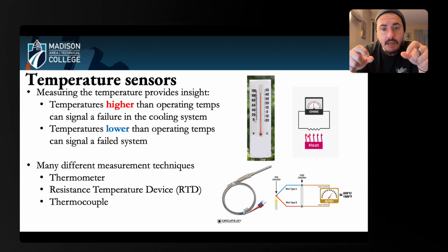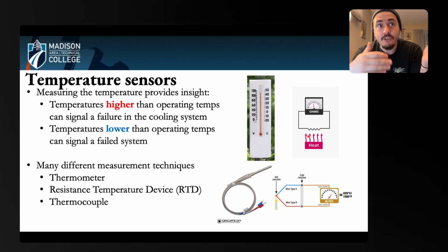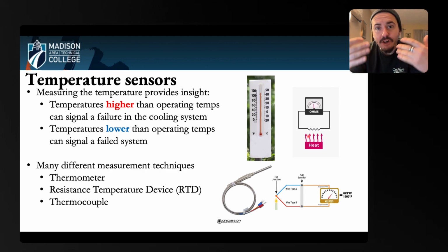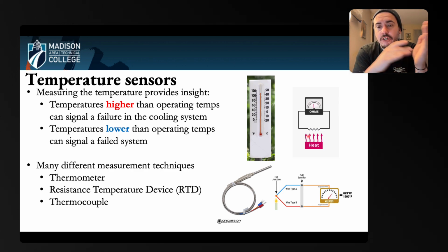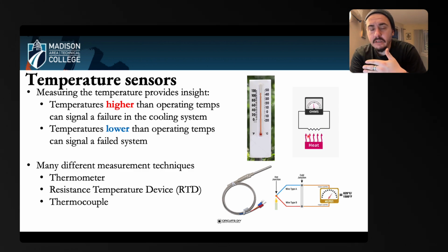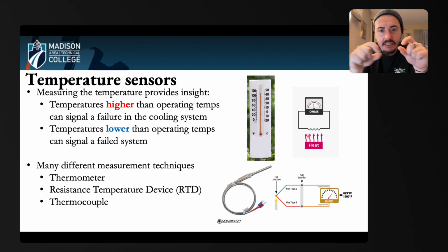Now that means that I can measure the resistance at different temperatures or measure the resistance and infer the temperature. So it'll be one resistance at this temperature, another resistance at some other temperature. I make a calibration curve, and then I can always measure the resistance at any time, and I can get temperature from that resistance measurement.